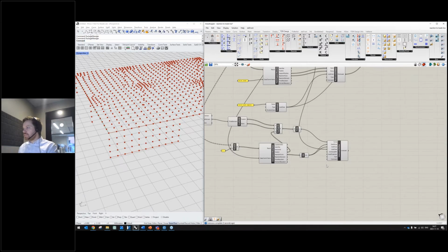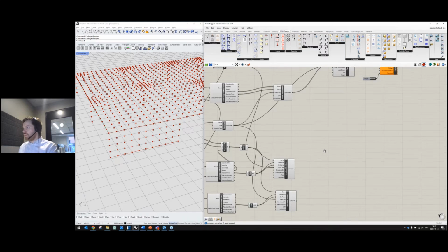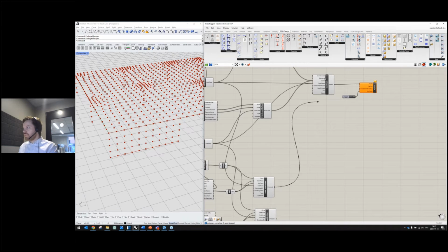And yeah, that's it. So let's copy this and do the same thing for the live load. I will just grab the live load over here instead, grab the results from the live load case, and I will place this into the live load export load case, my new load. Let's add this to the loads in the model